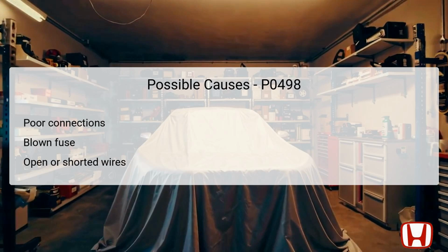In this case, checking the number B30 7.5A fuse located in the underhood fuse/relay box is essential. Additionally, open or shorted wires in the wiring harness connecting the valve and the fuse to the PCM can contribute to low voltage detection. Repairing any of these issues quickly can prevent prolonged malfunctions and related vehicle performance problems. A thorough examination of each potential cause is integral to rectifying the DTC.